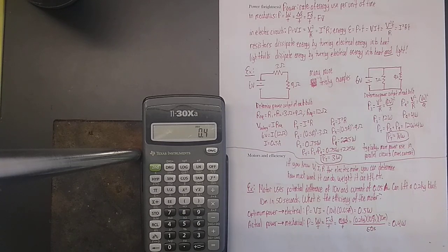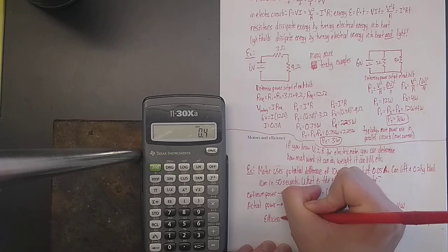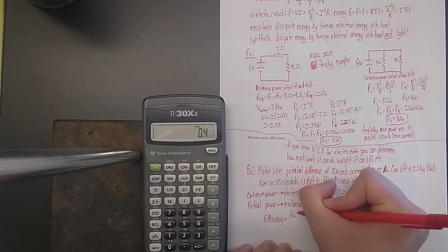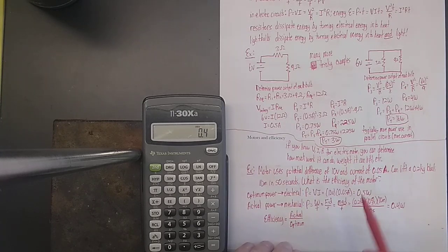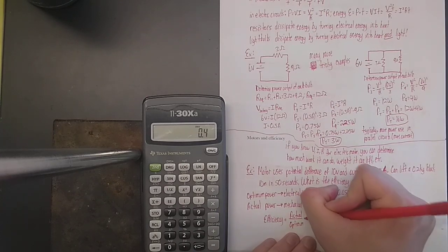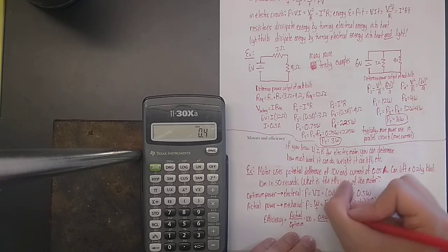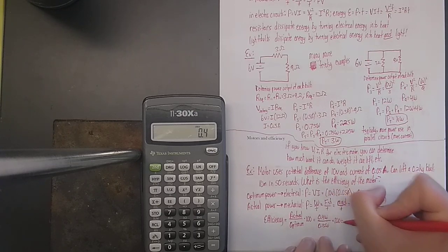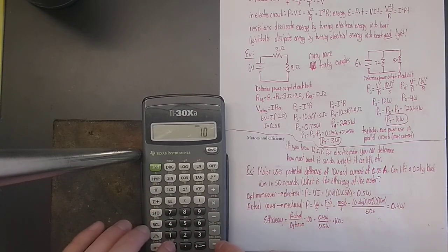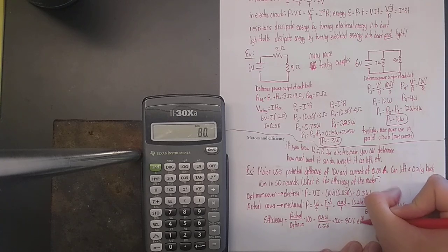Now, why is there a discrepancy? Well, it's because the motor isn't 100% efficient. The equation for efficiency is the actual output over the optimum output. This is how much we should expect, and this is how much we're actually getting. Then we multiply that by 100 to get a percentage. The actual output was 0.4 watts. The optimum output, what we thought we should have got ideally, is 0.5 watts. We multiply by 100, and we get 80%. There's no such thing as 100% efficiency, but this motor has an efficiency of 80%.